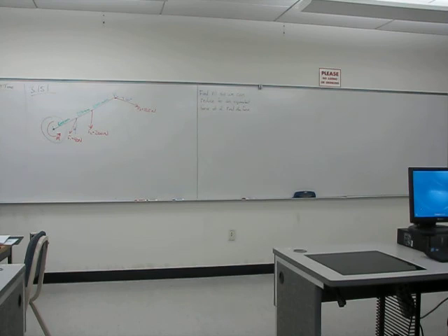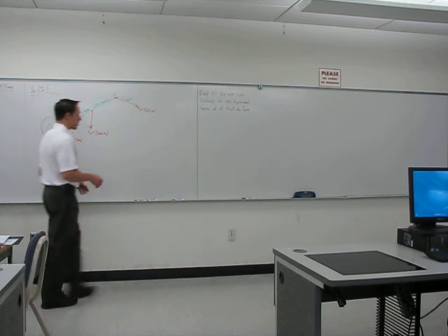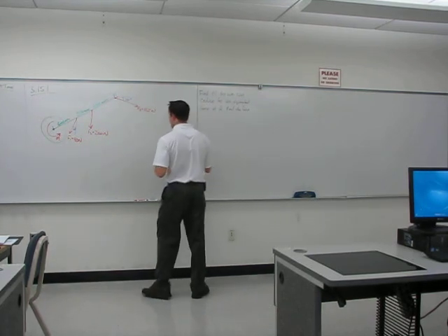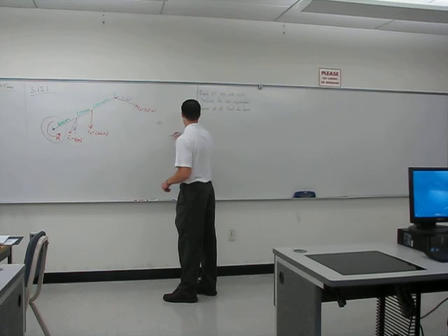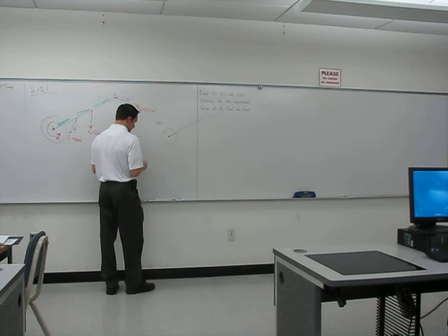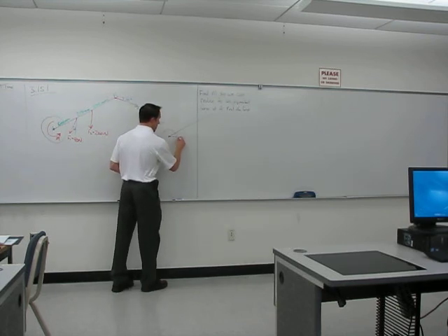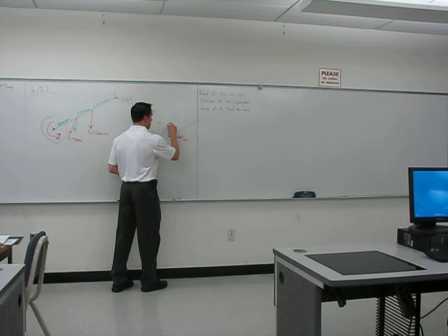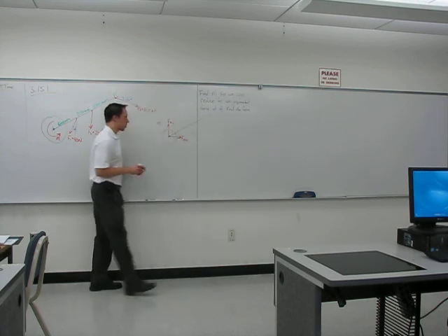So here's our job. Our job is to figure out what the magnitude of that moment vector should be so that we can reduce this system of forces to a single equivalent force at A. And then we should find that force at A. So in other words, they want us to take this picture and set it equal to, here's the rigid body, here's the point A. They want us to find a single force at A where we might have some FAX and FAY components.